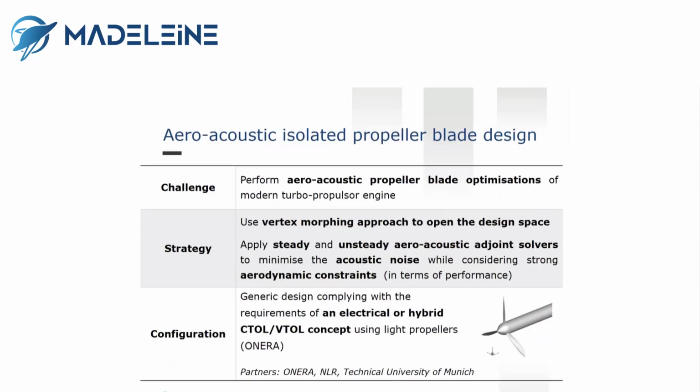Regarding the aeroacoustic problems, the first one is aeroacoustic propeller blade design. The idea and the objective was to design a propeller blade considering aerodynamic and acoustic performance at the same time. Our strategy here was, as for the previous test cases, to try to use some advanced parameterization techniques in order to really open the design space.